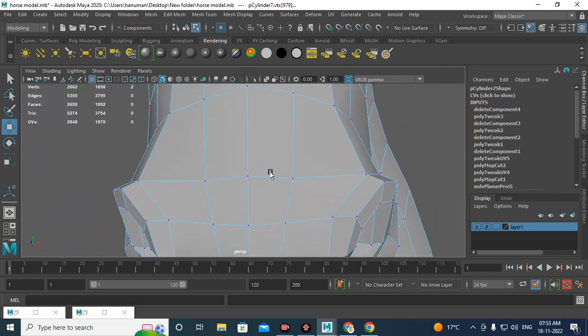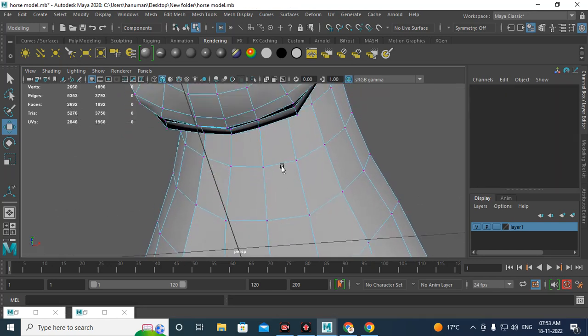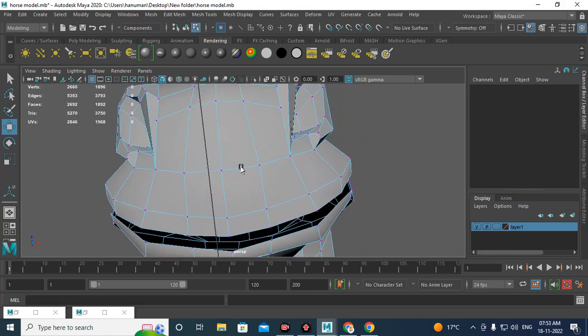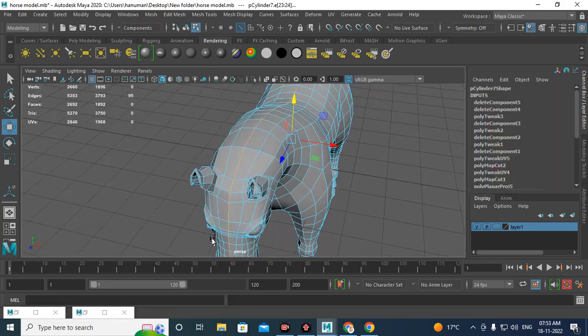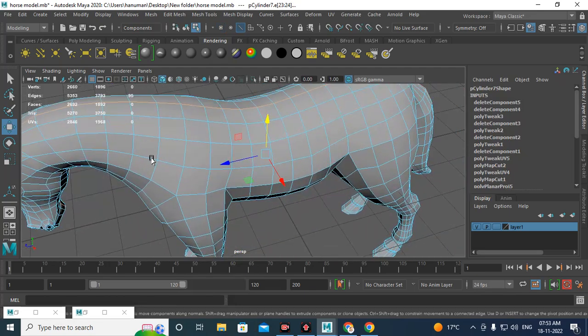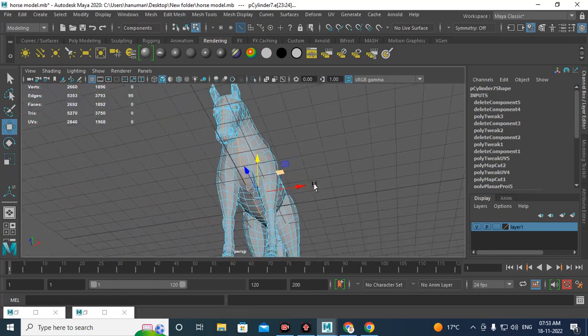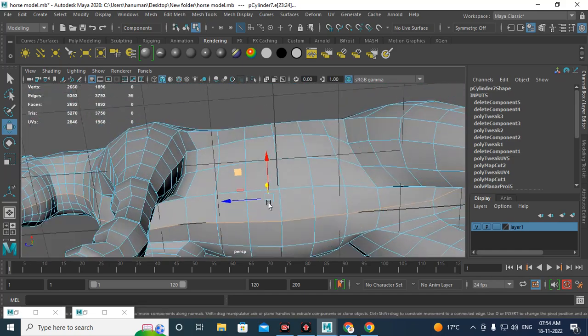Whenever we add the mirror, why does it create this? Because if the vertices are slightly crossing and not exactly at the center, then the mirror automatically generates a new vertex and attaches the opposite side to the extra vertex, if your particular vertices are not exactly at the center of the grid. Clear? So after the mirror we have to check definitely.